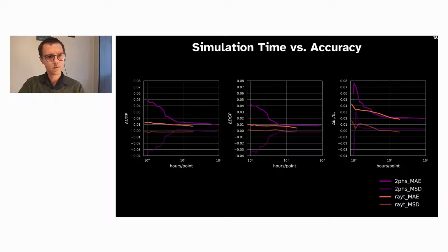The relative deviation for vertical illuminance steadily increases at lower times, but is still less than 5% in the 50-minute runs. This is mostly driven by low absolute illuminance conditions, which explains why this error does not visibly appear for DGP, which is heavily dependent on illuminance. In fact, this pattern of higher error at lower illuminance is to be expected in the ray traverse method. As ray sampling is driven by variance, small absolute deviations, which will matter for low illuminance scenes, are not targeted for additional sampling.